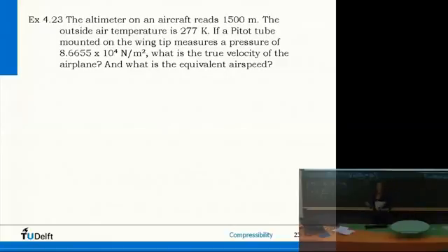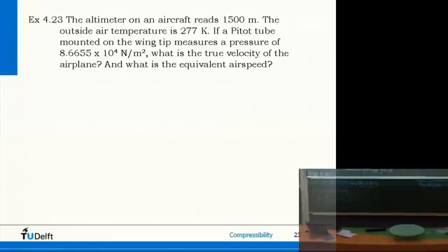So then, what pressure do we use, right? The strange thing is that the density we assume constant, the pressure changes a bit, so apparently the temperature also changes a bit, but we don't have information on how the temperature changes that bit, right? So what do we do? We have information on pressures at free stream conditions, so we use the temperature at free stream conditions.